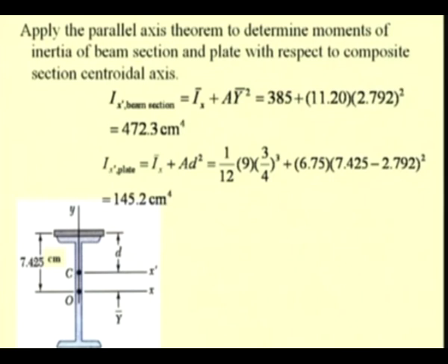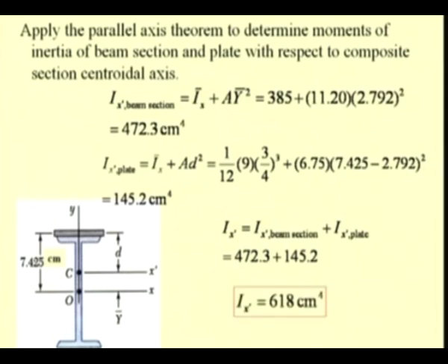So, now we can determine for the complete section as the sum of these moments, which is equal to 618 centimeter to the power 4. So, these problems illustrated how we can use this parallel axis theorem for computing the second moments of the area.